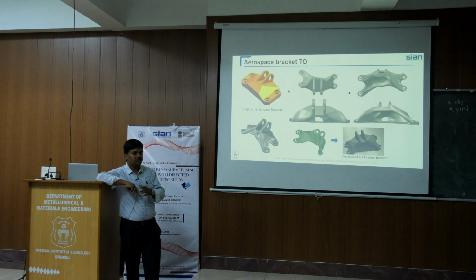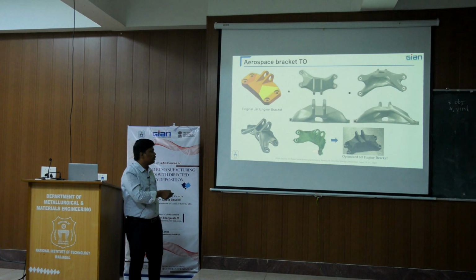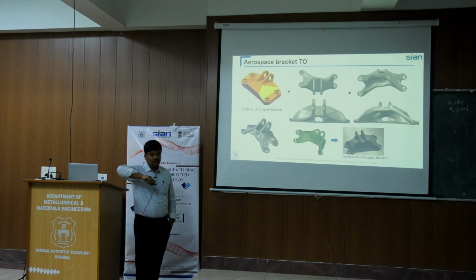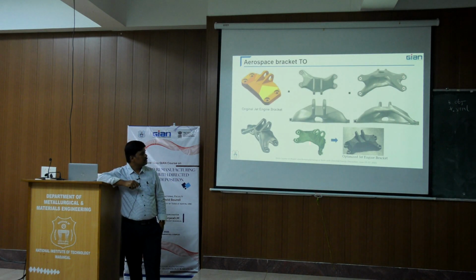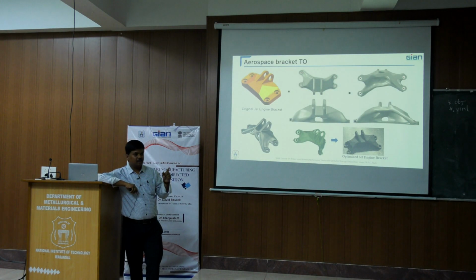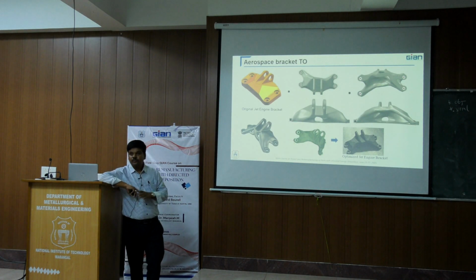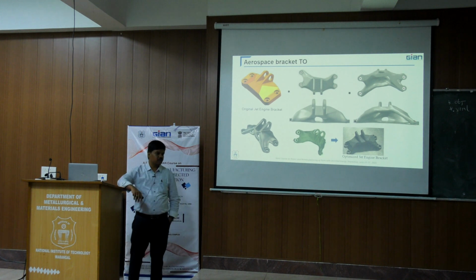This is going to be a best solution for topology optimization and weight reduction. This is the component we finally got with our tool and with the other software, the Hexagon MSC software. We got that final optimized bracket and we made it initially with PLA polymer using the FDM process. And then finally we printed it with our DED manufacturing, the powder bed fusion process.